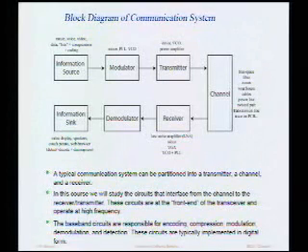And we generally put coding on the bits. The reason we put coding on the bits is we want to be able to detect errors in transmission, which can be very common for certain types of communication. As you can imagine, if you send information down a wire, it's probably going to be a lot better than sending information through the air, because through the air, the environment is constantly changing. There's multiple paths from source to receiver, so the probability of error is higher. So coding allows us to detect when errors occur and sometimes even correct for those errors.